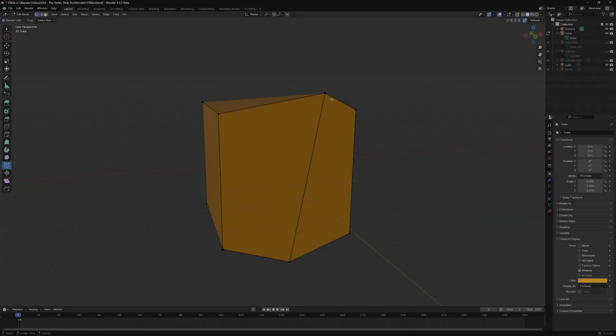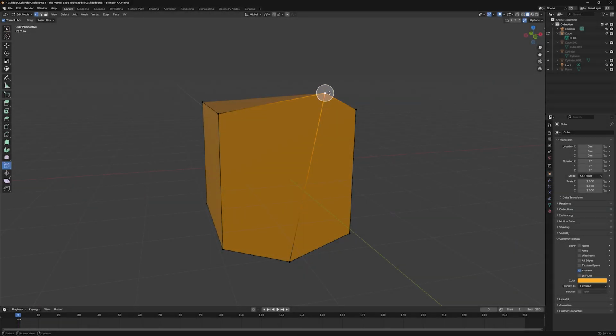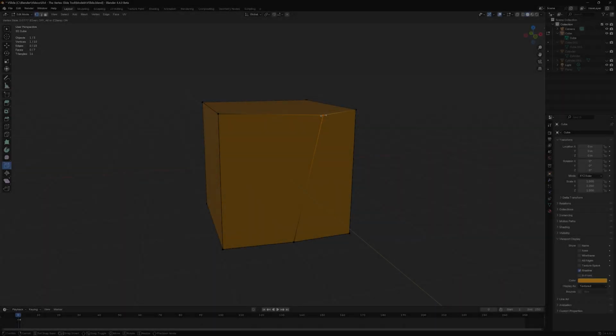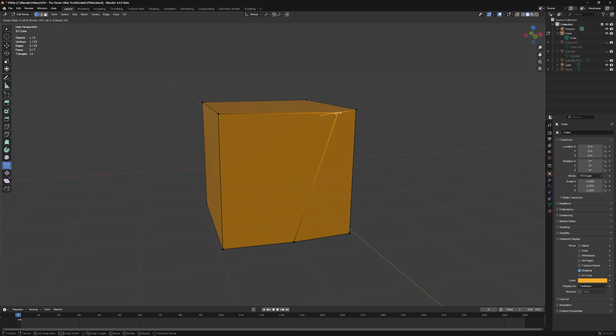Hold down Shift when dragging, and the move will be over a shorter distance for a given amount of mouse movement. This may help with accurate positioning in some cases. If we are sliding a vertex so that it is placed over some other existing vertex, switching on Auto Merge will ensure the two vertices are replaced by a single vertex.